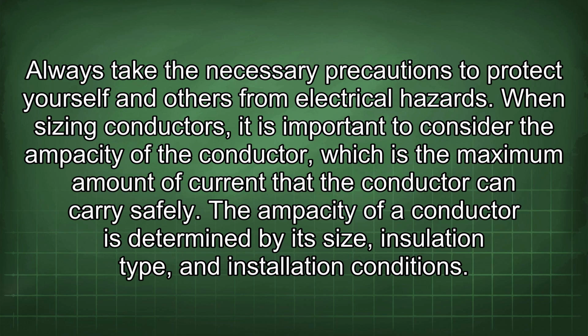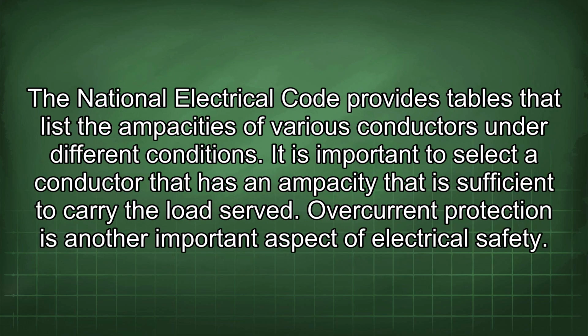When sizing conductors, it is important to consider the ampacity of the conductor, which is the maximum amount of current that the conductor can carry safely. The ampacity of a conductor is determined by its size, insulation type, and installation conditions. The National Electrical Code provides tables that list the ampacities of various conductors under different conditions. It is important to select a conductor that has an ampacity that is sufficient to carry the load served.